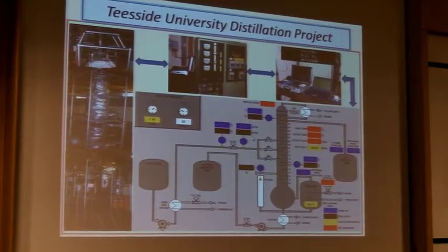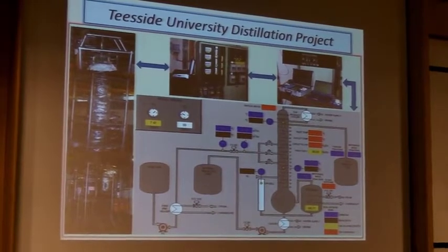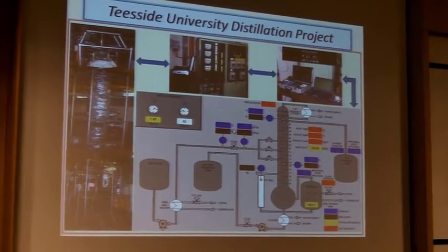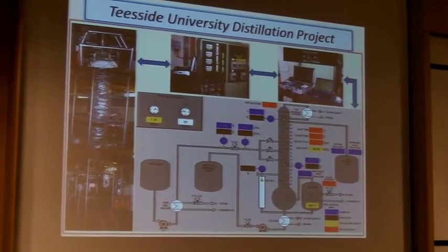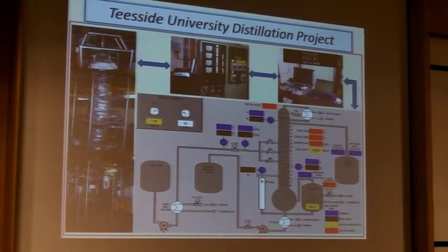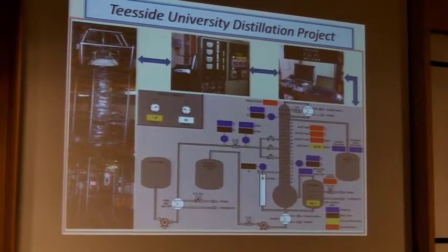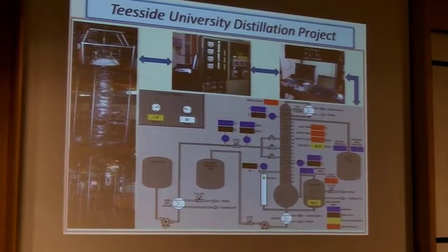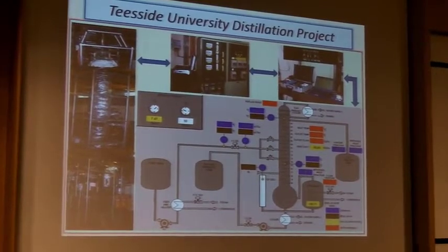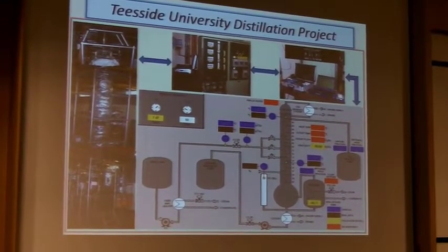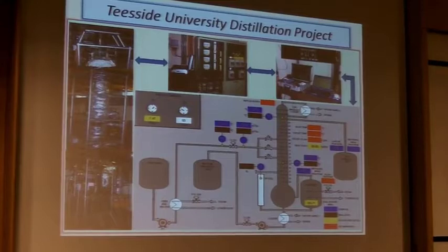We use their software to do this. And basically what we're doing is you can compare, these are the simulator values, and these are real values. So you can build your mimic to take real data in, and your simulator is also prompting you in terms of the information that the simulator considers to be the optimum value. So it's sort of prompting the operators to where the deviations are. When I say online simulation, it doesn't necessarily mean to say we've closed the loop in terms of allowing it just to go and do the adjustments itself. But there are people who have closed the loop. So it's an online, offline situation.